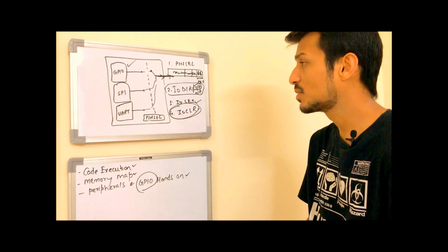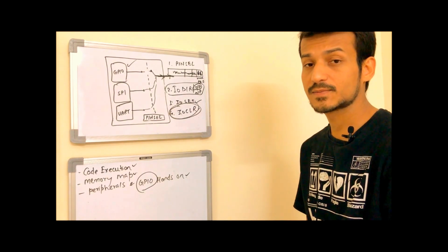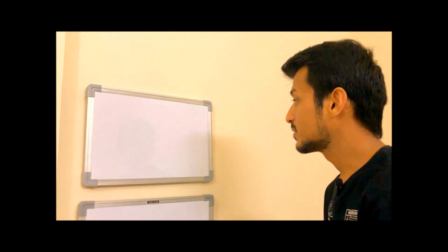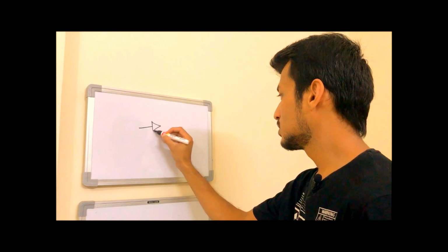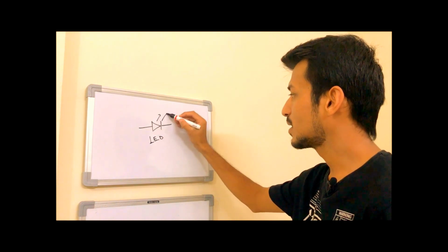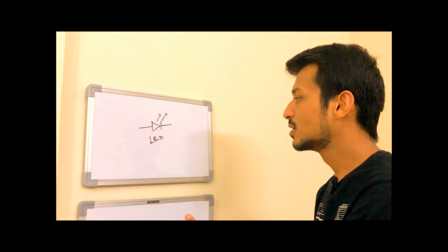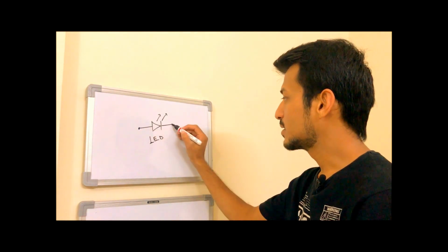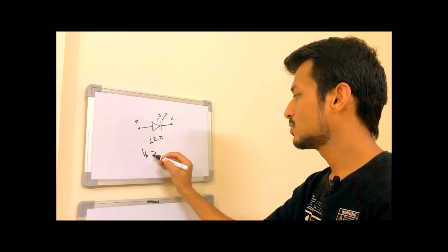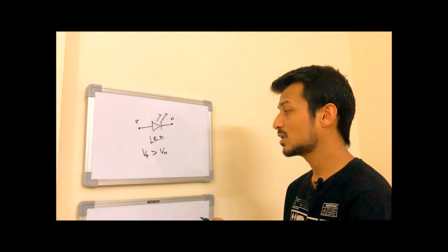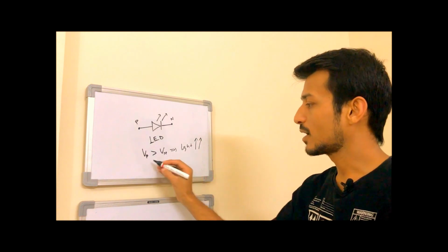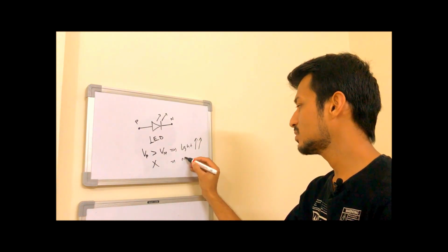Now let us go to my laptop and check this practically. Before we download the code to the development board and see the LED glowing, I'll tell you how the LED is connected in my board. LED is nothing but a light emitting diode which emits light when it is in the forward bias condition. What I mean by forward bias is this LED has 2 terminals, P and N. When the voltage of this P is greater than the voltage of this N terminal, then you will have light. And when this condition is not met, then there will be no light.